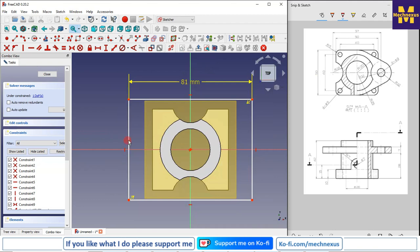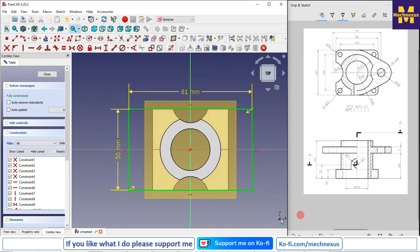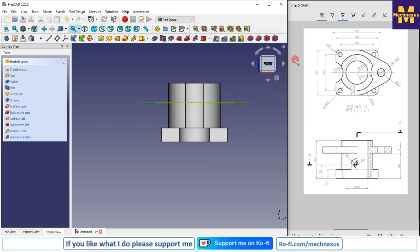So I can give the dimension or I can make it a coincidence, but better I will give the dimension. It is 50. Now I will close it. Now its thickness is 7 mm, which we can see here. So it is perfect on my datum plane.